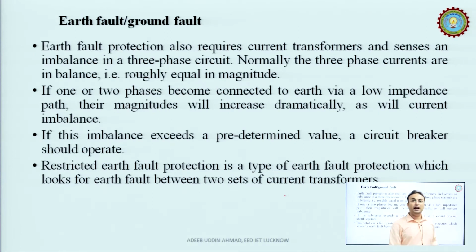Now, again there is earth fault or ground fault protection. Earth fault and ground fault protection is very common. We have earth fault relays from the domestic point of view, and also from the commercial point of view. This protection is very common because earth faults are very common in power systems. Earth fault protection also requires current transformers and senses an imbalance in a three phase circuit.